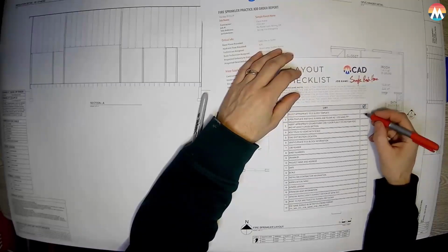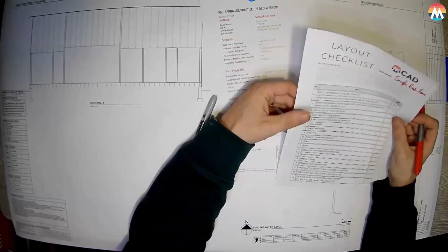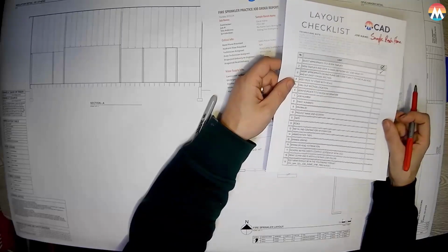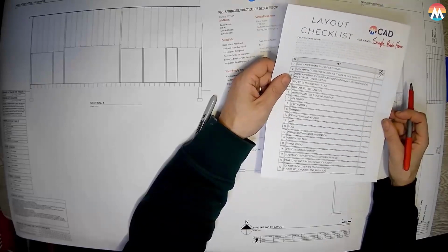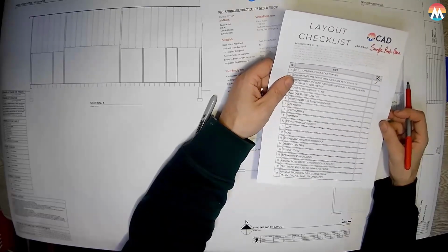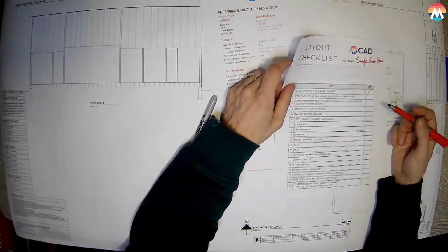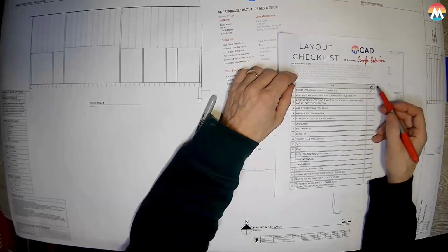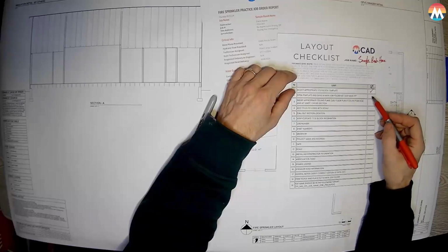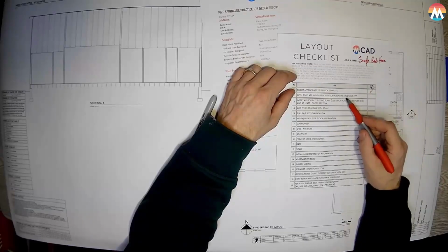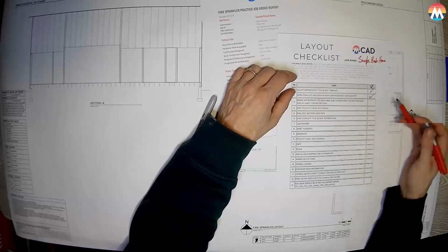Select appropriate title block template. Now that's already been done. We provided you with the appropriate title block template. This layout checklist is for all of our sprinkler jobs. And we have 3 fire sprinkler templates. One is for 13D jobs, which the job we are doing in this course is a 13D job, and that's the template you were provided. We also have a separate template for 13R jobs and for 13 jobs. So that is the scenario where you would have to choose the appropriate one. But for this course, it's already been chosen for you. Hopefully you were able to download that, open it up in your CAD program, and save it as the name of your job, which would be Sample Ranch Home and FP1. So I'm going to assume that you did that, because we're at this point where we have a piece of paper.